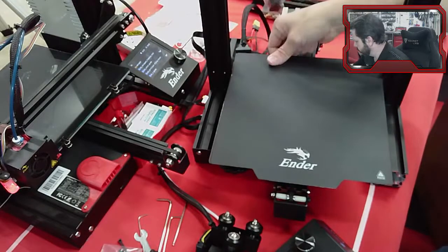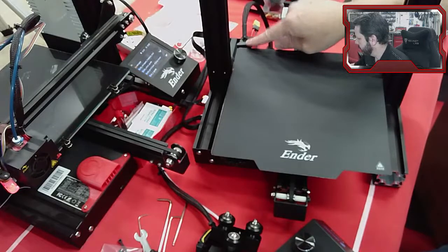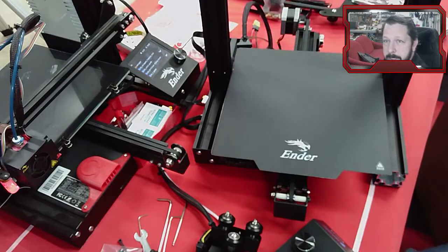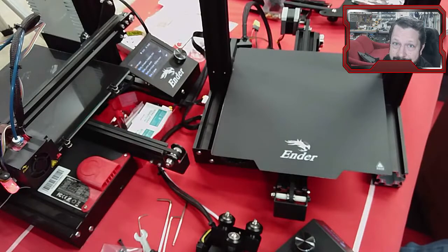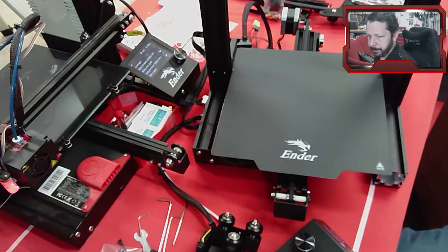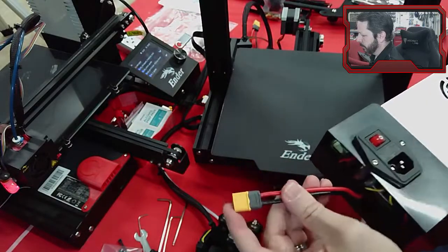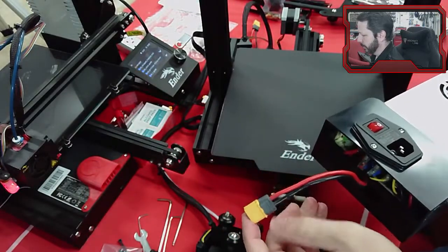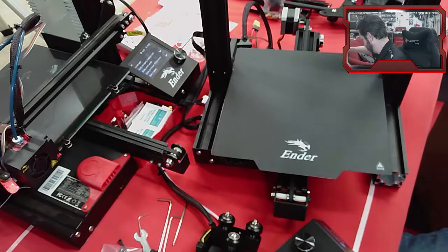But since this moves back and forth all the time, then without a strain relief over here, those solder connections will get loose, and a loose solder connection requires more power to be sent through it, electrical power, and that more power creates more heat, and so it creates this cascade problem. Same thing on here. So you do want to make sure that you have crimped connectors, not soldered. And I don't think anybody's shipping them with the old soldered on connections anymore, but just check.